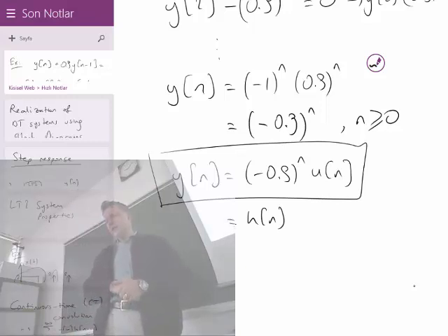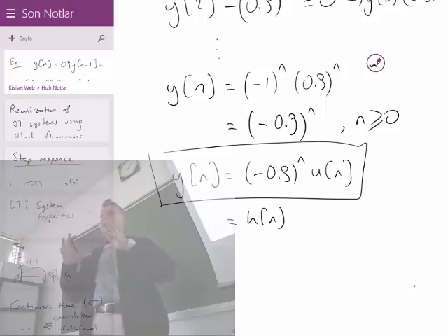For other more complicated difference equations, it may be a little bit more cumbersome. But of course, since I have shown you a simple example about how to proceed iteratively to develop the impulse response and generalize it, there is a strong possibility that I may ask you a little bit more complicated one in the exam. What could it be? It could be a second order input and the first order output, for example, like this. So the input could also have some iteration, and the output could also have some iteration. This has nothing to do with the block diagrams that we are covering. I just entered into a parenthesis, and I'm giving you some hints about how to develop impulse responses.